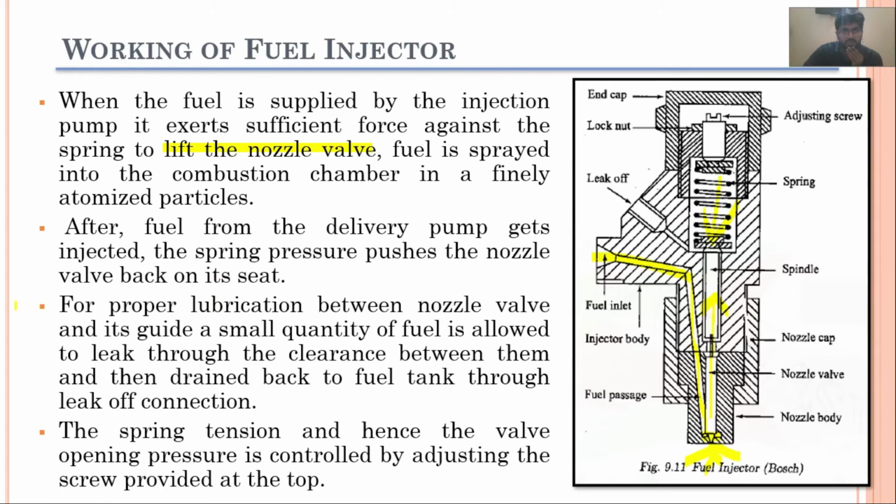This is a very important point which I am going to discuss now. For proper lubrication between these moving components, you can see that we have small passages here. Between these passages the fuel which is coming from the fuel inlet will be flowing, and it will work as a lubricant between these moving components.